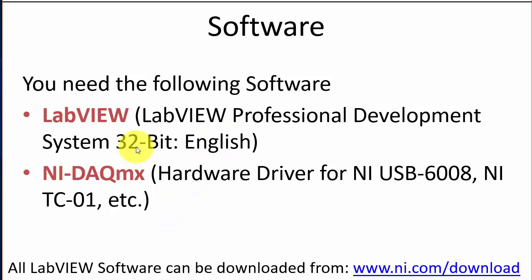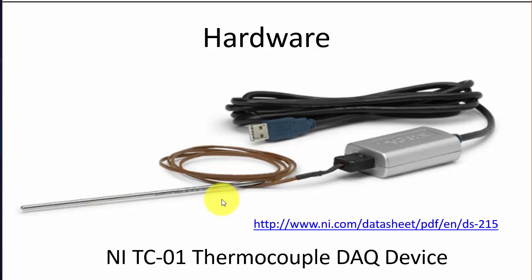Software needed: of course we need LabVIEW. The latest version is LabVIEW 2015. We will also need the NI DAQmx software, which is a hardware driver for hardware used with LabVIEW. In this case, we will use the TC01 thermocouple device. Hardware: in this video, we will use the NI TC01 thermocouple DAQ device. For more information, you can click on this link to see more information about the device.